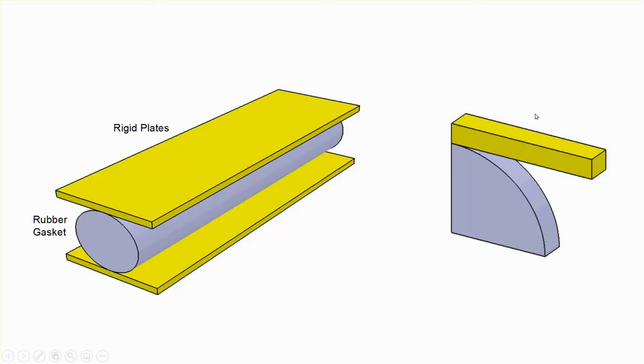So what we can do is take a sector of this. First of all, notice that because of the symmetry, all you need to do is model one fourth of this circle, okay? And then because it's very long in the length direction, it's a plane strain condition. All we have to do is take a little sliver of this out, and the length of it actually doesn't matter. Plane strain condition usually assumes that it's 1 unit long, but that's totally irrelevant.